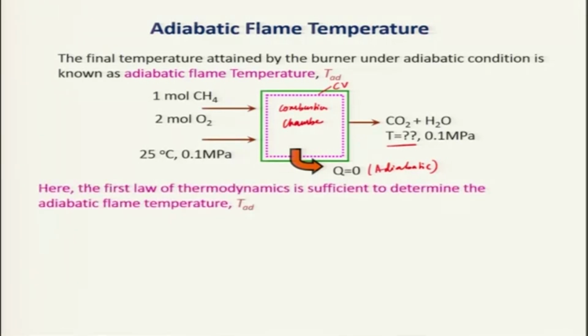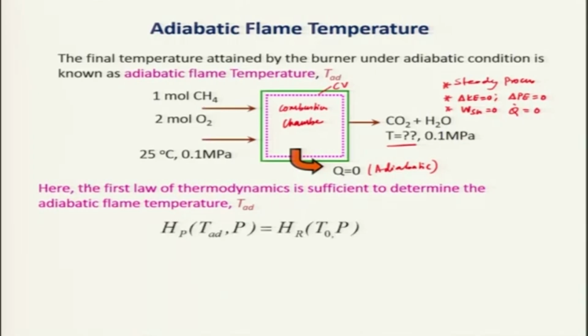For that we will have to invoke the first law of thermodynamics, considering the process to be a steady process, with change in kinetic energy 0, change in potential energy 0, no shaft work, and adiabatic. Considering these assumptions, the first law states that Hp is equal to Hr.